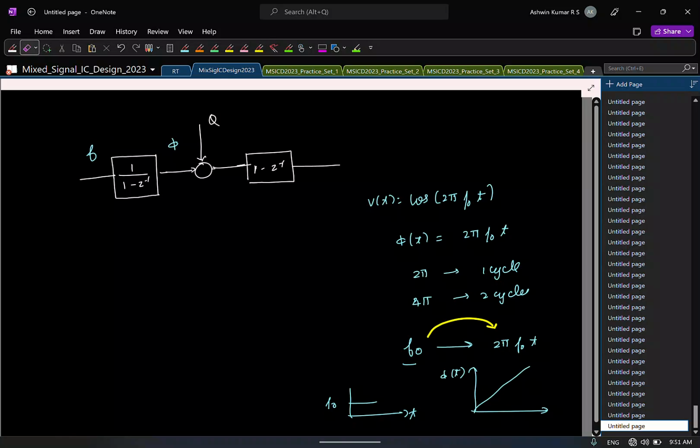Now I want to digitize a voltage signal, right? Because my signal that needs to be digitized is voltage. So I have to convert voltage to frequency. So what can I use? VCO. I hinted at it in the last class. Again, you don't have to understand how a VCO operates. It is just an oscillator whose output frequency, if I call it omega out, is some constant, I will say k VCO, times the input voltage V. That's all.